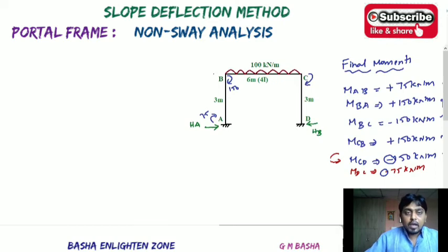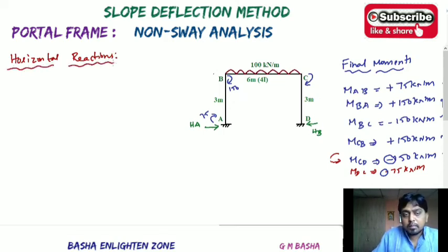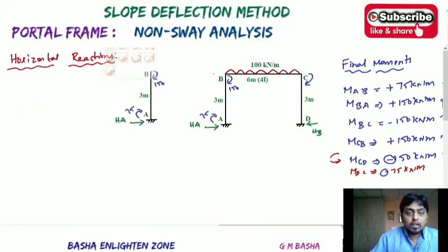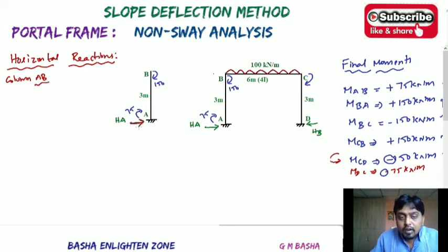Okay, see here, I am calculating the horizontal reactions, and I will show you another procedure: just resolving the force to one end. We already solved so many problems based on that, so that is very easy. Just take the column as it is. So we are calculating the reactions for column AB. Here just assume any one direction, like horizontal direction towards right.